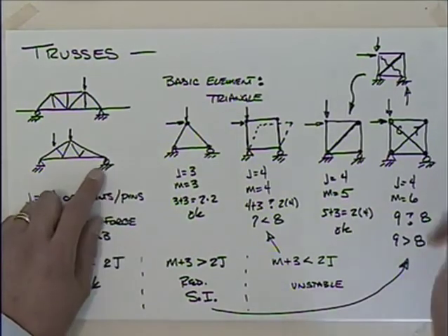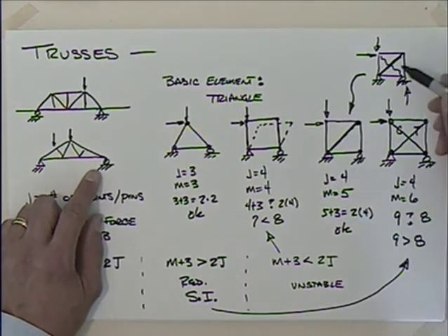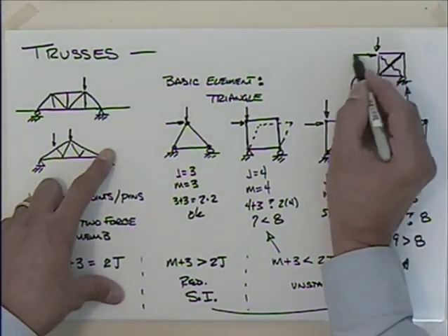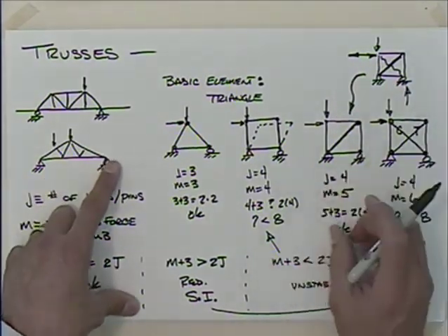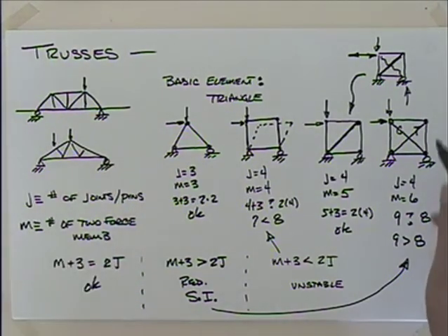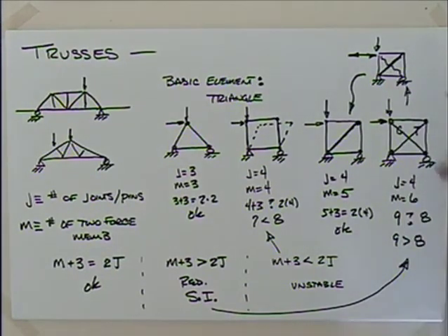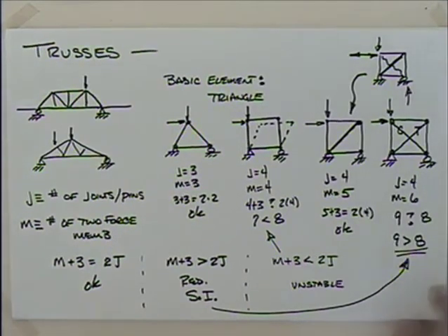Okay, so depending on how the members are laid out, this may or may not be a problem. The reason I bring this up is we do this all the time in construction. Putting thin rods or cables there is a very efficient way to do this, because a lot of times we don't necessarily know which way the load's going to come from, particularly these lateral loads, whether a wind load or an earthquake load. It could be coming from one direction or another, so we could put the braces in there and have a very light, very efficient system. And we can still analyze that, because when it goes into compression, the thin brace is not going to do any good. But if these were both heavy I-beams or something like that that would hold a lot of compression, we would be stuck at that point.